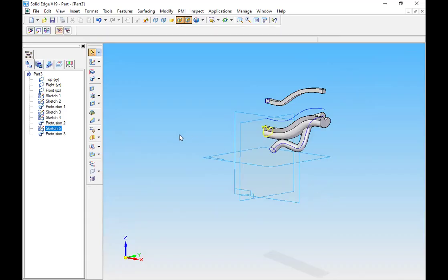Similarly, we have cutouts. Okay. You have drawn a profile here, right? I'll do a cutout now. See, swept cutout, lofted cutout, helical cutout. In what manner we are adding the material, in the same manner we can do the cut also.